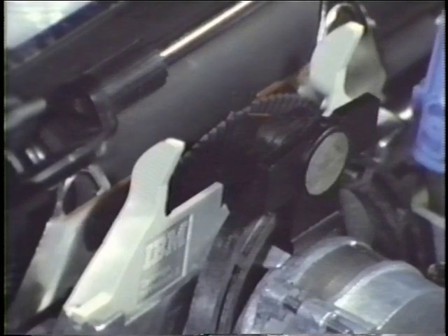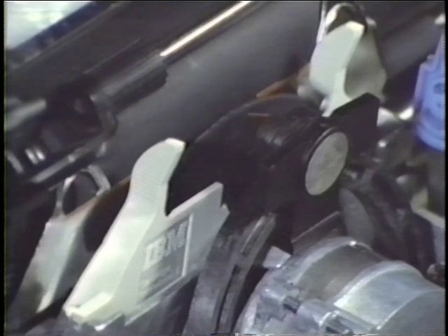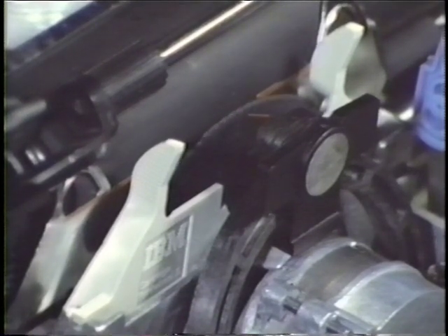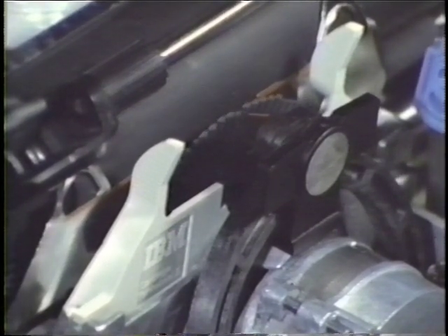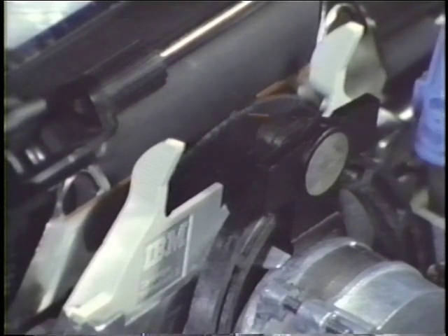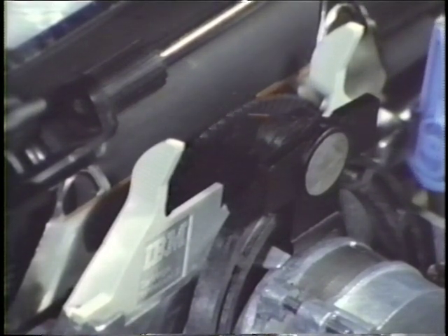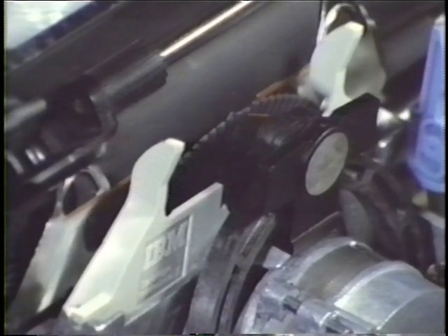The printer board does 5 things during POR that involve selection. The first thing the printer board does is to spin the selection motor to ensure that the selection motor hub is engaged with the print wheel. The second action of the printer board is to home the print wheel. The third and fourth actions are to electronically sense the pitch and impression level of the print wheel. Finally, the printer board lightly fires the hammer solenoid. When power on reset is complete, the print wheel is detented in the home position.